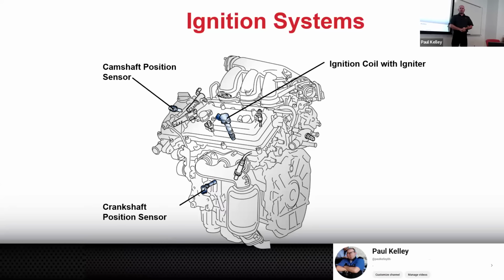You've heard the method, right? The KISS method. That doesn't mean kiss everybody. It means keep it simple, stupid. Like you got 6 coils on this engine. If you think you got a bad coil on 3, swap it. In fact, I would take it a step further. Do you think it could be the spark plug too? Spark plug could cause a potential misfire, right?